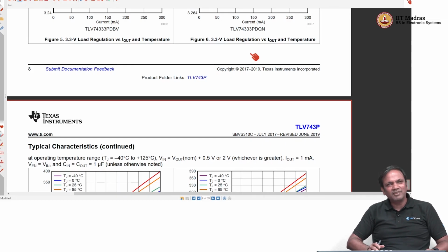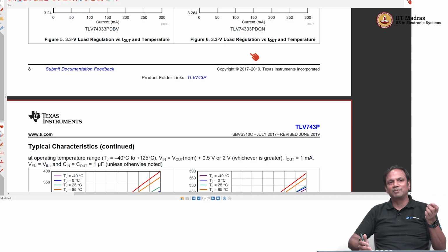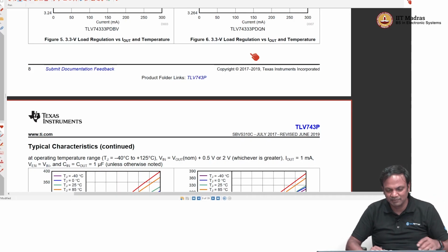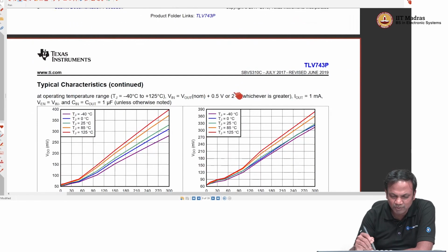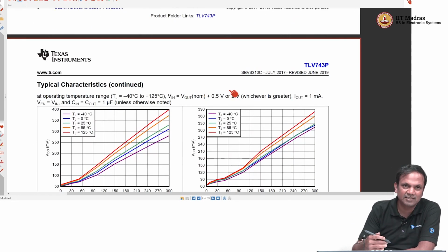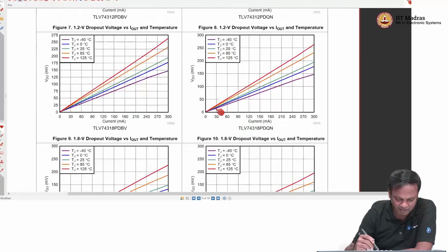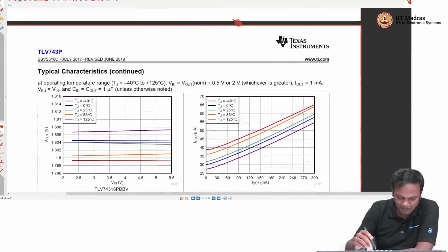Then what you invariably end up doing is saying, okay, let me open the data sheet for this component and see whether this behavior is explained. Maybe there is a temperature variation that you are surprised by, and then you find out, oh, okay, this is how this component behaves. So, it is important to take the time to review the data sheet to be able to tabulate how the different parameters behave, right.